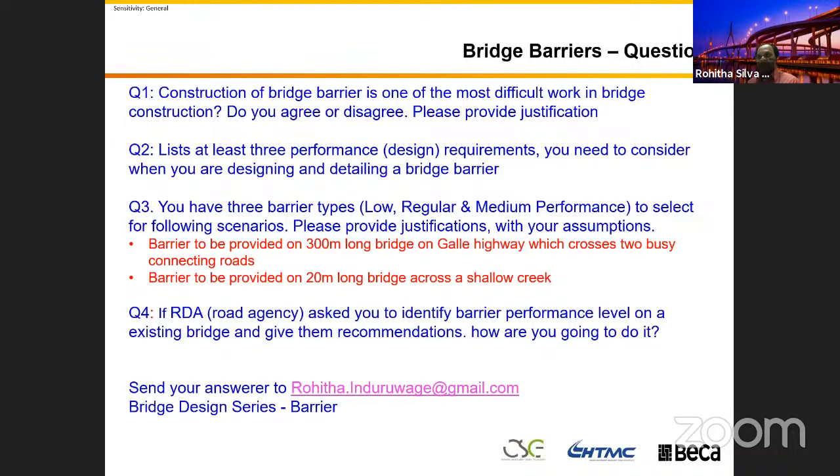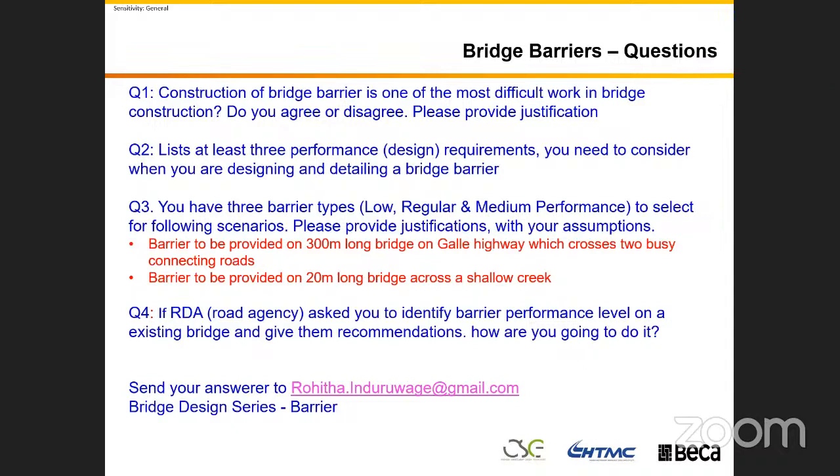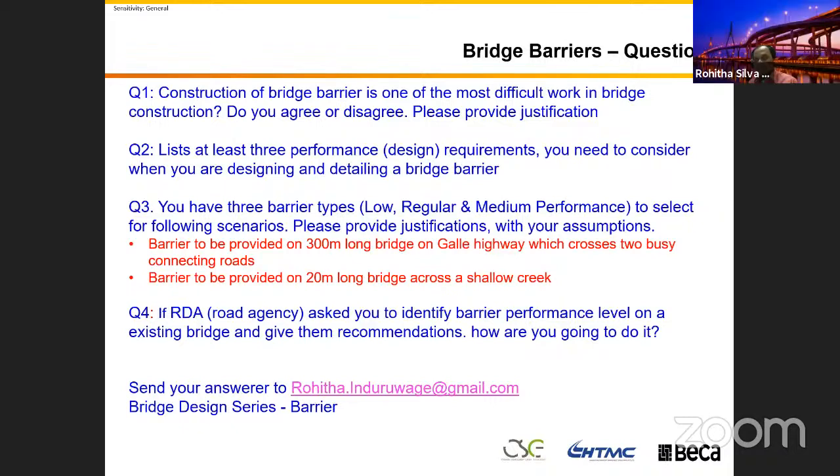12 to maybe about 15, 16 meters of soft clay, like when you just leave the casing and it goes straight down. I think we got a first sand layer from the top of the platform level to that level close to 30 meters. And the final question on that was, when the piles were poured, were they poured in segments or continuous? No, continuous pour.